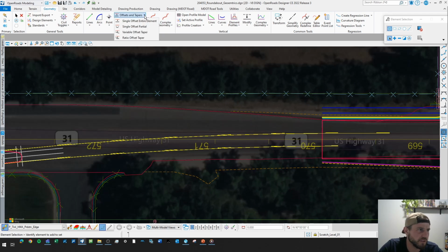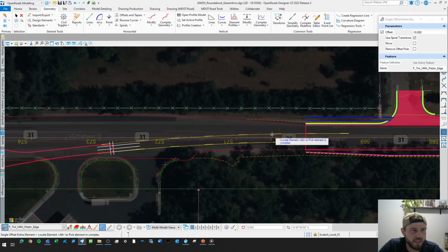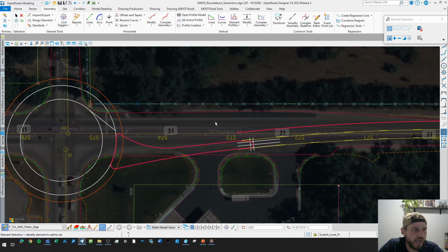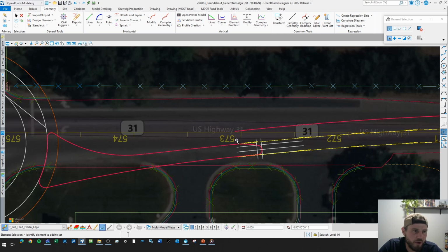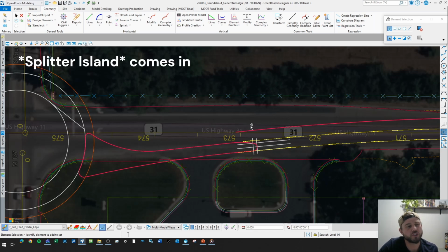For this first one, I really like to offset this entire element. We'll start out at that 12 feet, so definitely want to connect into that. Don't need to mirror it for now. But we do need to widen this, even in terms of single lanes. Typically you're at about 14 feet by the time the ICD comes in. That's going to be based on your design vehicle, so that will change.